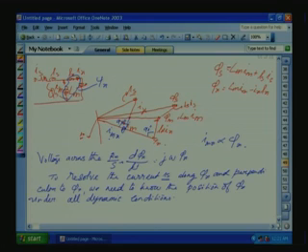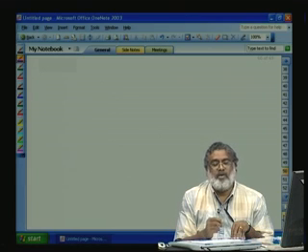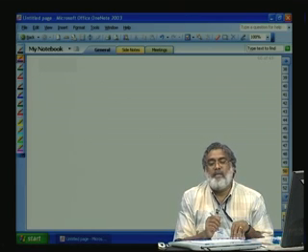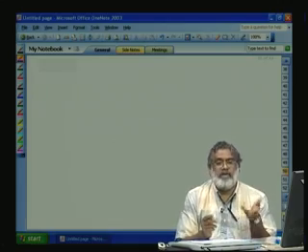Same as in a separately excited machine, the flux is kept constant, and we control the orthogonal component for the torque variation. So, let us study the dynamic equivalent circuit for the induction machine. Let us go to that one. From there, we will derive how to resolve the current IS along psi r and perpendicular to it. This is called field oriented control, the famous vector control.